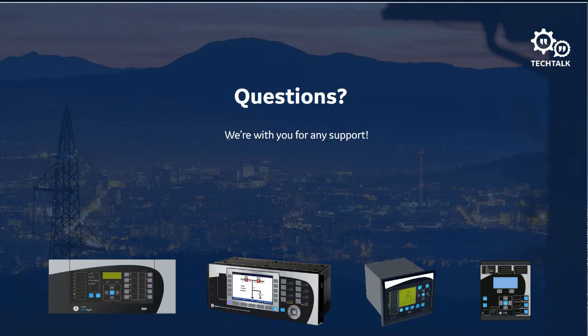You're right. What you connect to the relay, you're connecting those three CTs. You're not connecting sequence networks. The relay will use those same equations that we use in that third or fourth slide to calculate those sequence components. It can build negative sequence overcurrents, things like that.